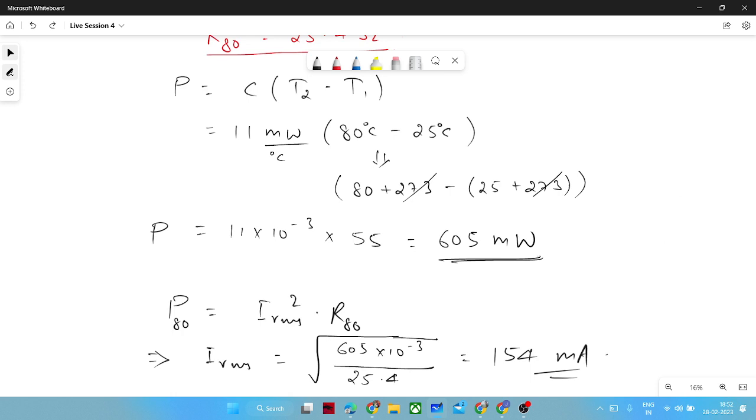Yeah, please go ahead, Vinay. I have a doubt on the peak voltage. Suppose we have a 230 volt RMS input to a rectifier. Without any inrush current limiting method, the peak voltage will be 325.27 volts. Suppose we use the resistive method of inrush protection, what happens to the drop across that resistance? Because the peak voltage will definitely get reduced, right?